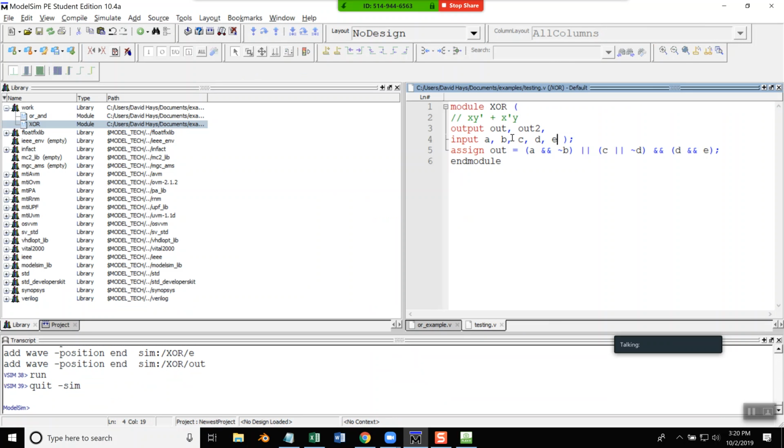Okay, so then you can have multiple assign statements too down here. So it's like you got a variable. You can think of these as variables. You got A, B, and C coming in, and instead of them being like values, they're like voltage coming in. It's going to be 1 or 0. Your output is E. That's like a variable. It's going to give you your end result. And then you got the wire D, and we'll talk about the wire D here in a second. Then you assign this, and these are just comments down here.